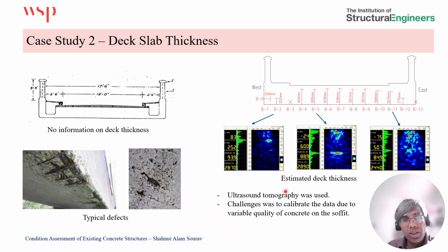I should mention here that we could not employ GPR to get the element thickness, mainly because there is highly congested reinforcement in the decks, as well as a lot of voiding that did not help the GPR data.